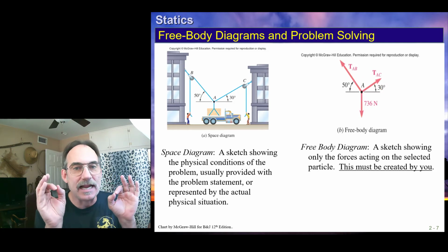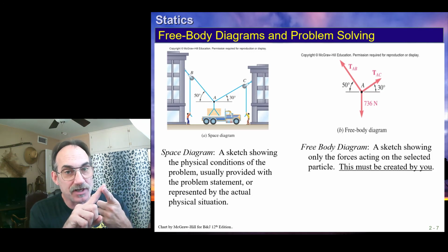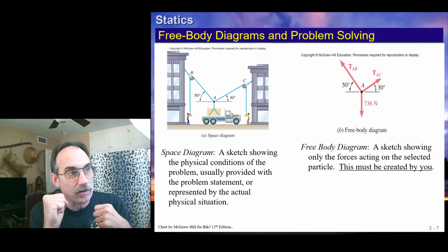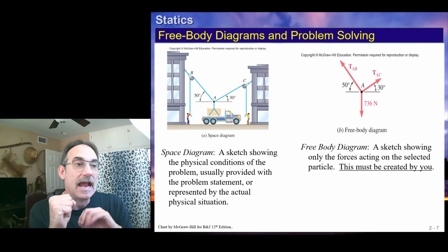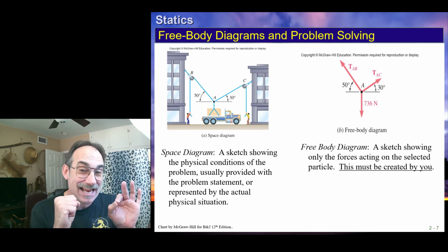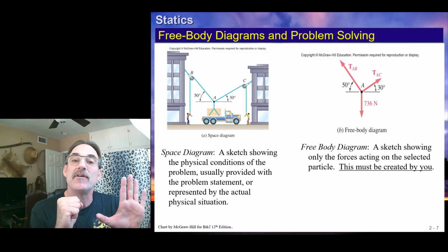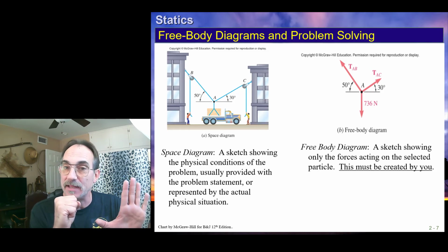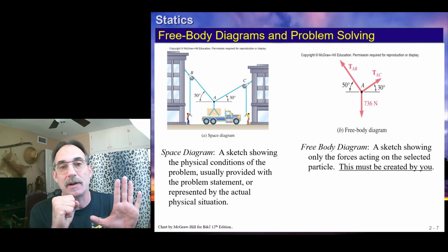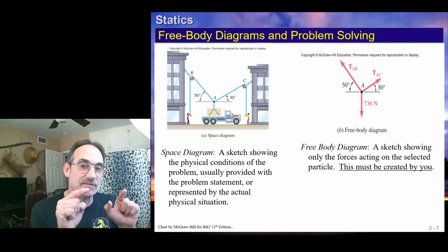If we fail to recognize the idea that those pulleys are frictionless, that the cables carry only tension, that we're going to focus on a particle, and all forces going through the particle, and that the sum of those forces are going to have to be zero if that's all forces acting on the particle, all action and reaction pairs, then for that to be an equilibrium, which means static equilibrium, which means it's not accelerating, the sum of any and all components has got to be zero, which means the sum of the x components better be zero, the sum of the y components better be zero, and we're going to use that principle to solve this problem.